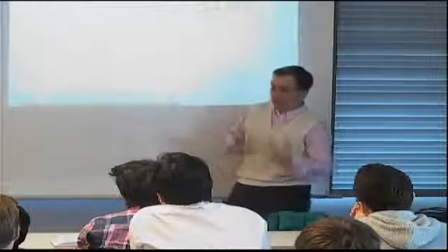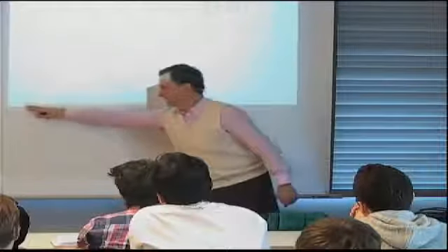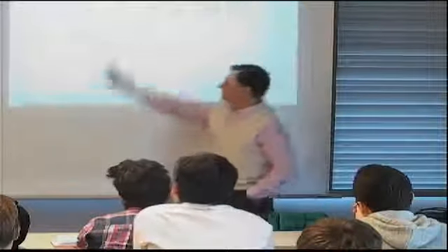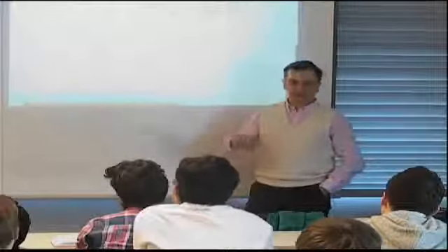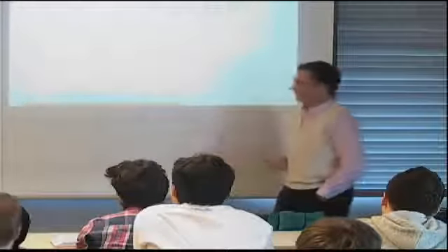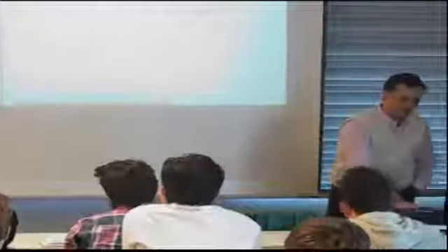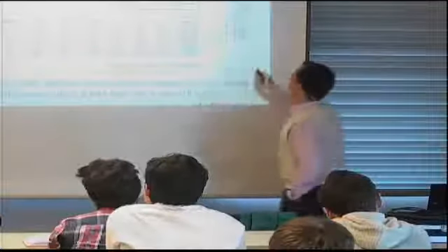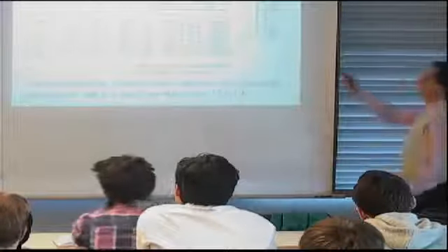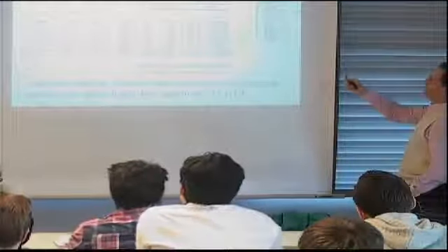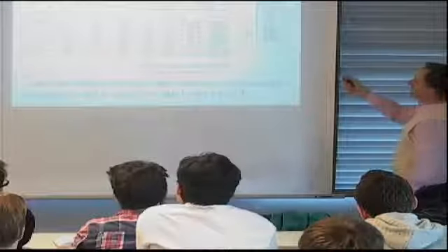And I'm saying, I don't know exactly how to account for it, other than, instead of treating this as a completely large member, I would split it. That divides my B in half, and it would still be reasonable because of this entire stiffener supporting the skin at that location. This is all open to debate, and I like your argument, and it would be worthwhile trying to come up with a better model to see if indeed this kind of ratio is as bad as it appears or not. One simple point is that these ratios are not only less than 1 for everything that does not fail, but significantly less than 1.